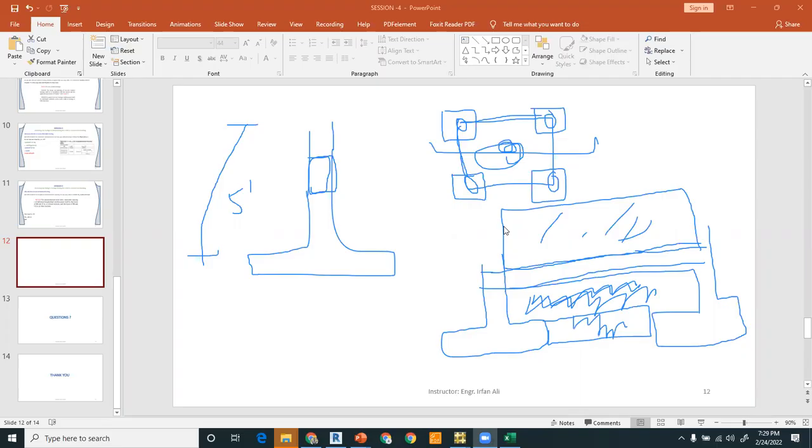Do we only extend into another side of the footing? Thank you. Right, you have to satisfy all of the requirements of development length of the rebars. For example, I'm still not getting your question very clearly, but for example, this is the one footing and this is the other footing, right? So if I'm taking your question right, you have to fulfill the development requirement over here, you have to provide hooks, right?